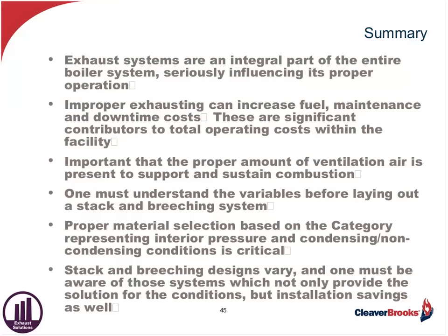Can you recommend a good draft inducer manufacturer? Well, I can take that. Yes, a couple that I've come across throughout the years. Exhausto makes an excellent induced draft fan, and most of the Exhaustos that I've seen mount in the vertical, oftentimes right on top of the stack. The other company that I've had good experience with is Turnlund. I've seen those in the horizontal breeching, but I think they also make a vertical appliance.